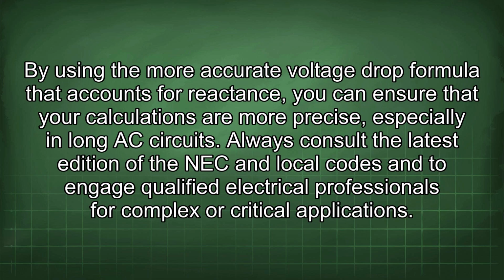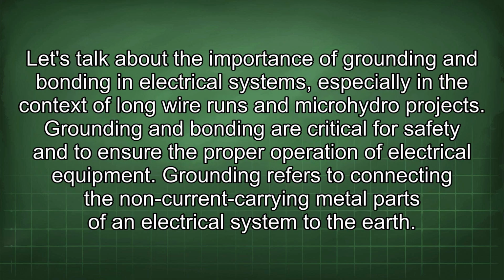By using the more accurate voltage drop formula that accounts for reactance, you can ensure that your calculations are more precise, especially in AC circuits. Always consult the latest edition of the NEC and local codes, and engage qualified electrical professionals for complex or critical applications. Let's talk about the importance of grounding and bonding in electrical systems, especially in the context of long wire runs and microhydro projects.